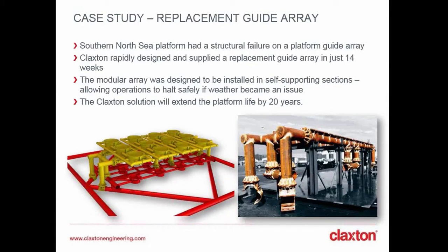This is another case study for the replacement guide area for a splash zone level. What happened was the splash zone on one of the offshore platforms was, obviously, because this level is subjected to seawater exposure and high levels of lateral loading from the conductors, in this case, that whole splash zone level was corroded to the point that it needed to be replaced in its entirety. So the first thing was to carry out a very good survey, basically to determine which structural elements were still sound, in good condition, that we could use to support the replacement guide.